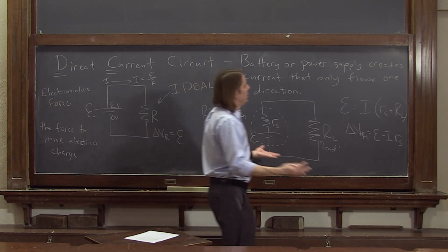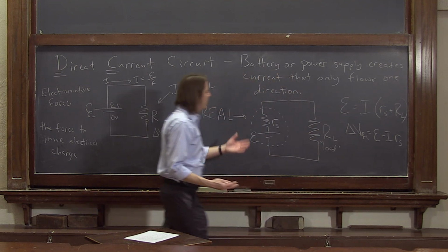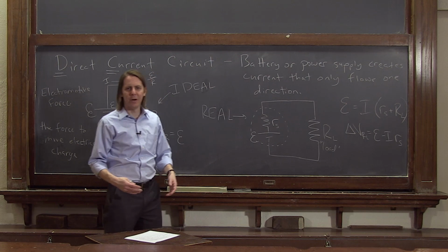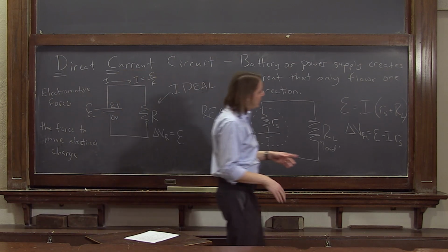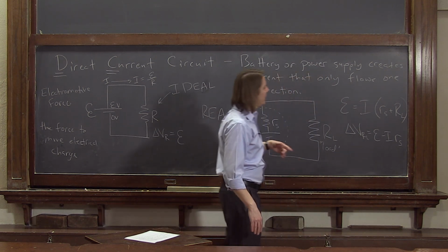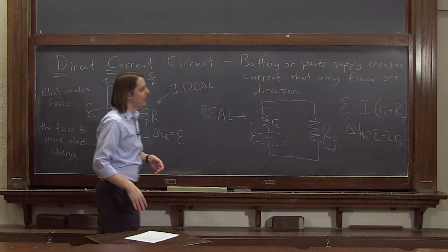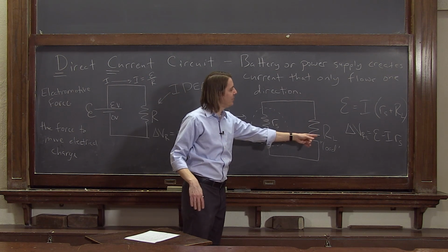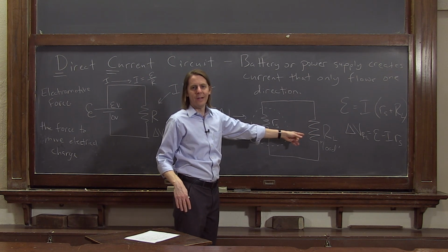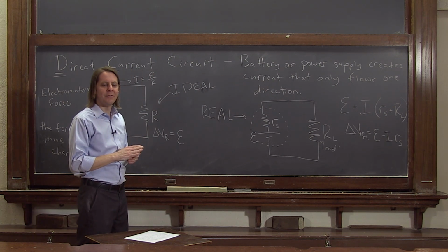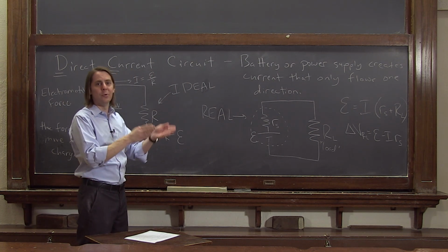So you might say, okay, that's not a big deal. Just every battery, you know, you lose a little bit over R_S, so instead of a 9 volt battery, it's an 8.5 volt battery. But what's unusual is it depends on the current. See? It's not a constant amount of voltage you lose. The amount of voltage drop you lose from the battery depends on how much current is flowing, which depends on our load. Okay? So no power supply or no battery really is a truly constant source of EMF. It actually depends on what it's doing.